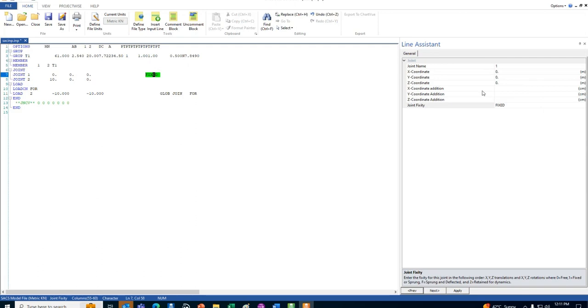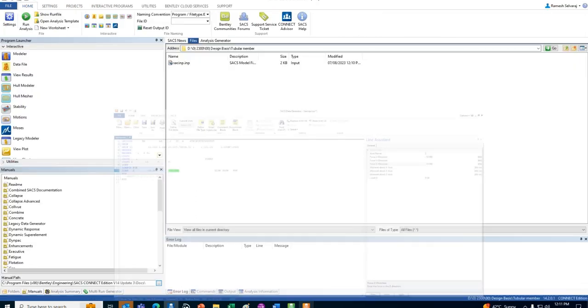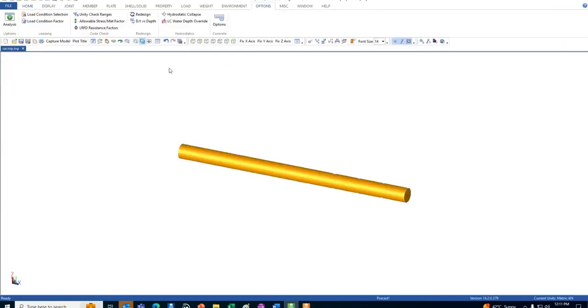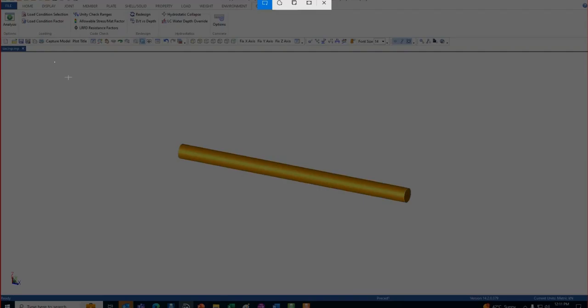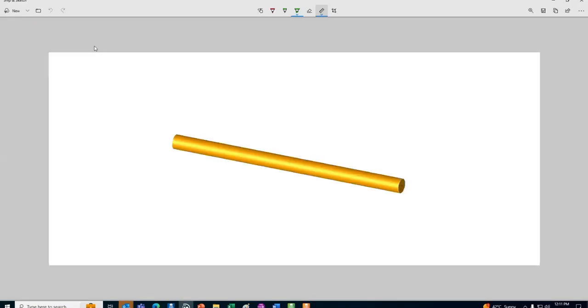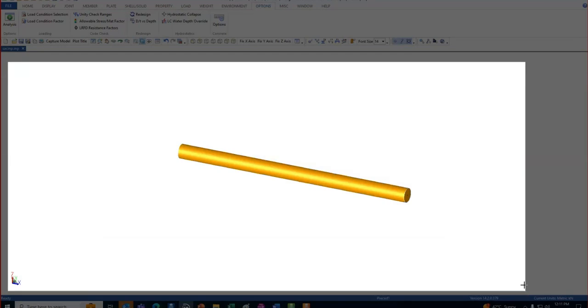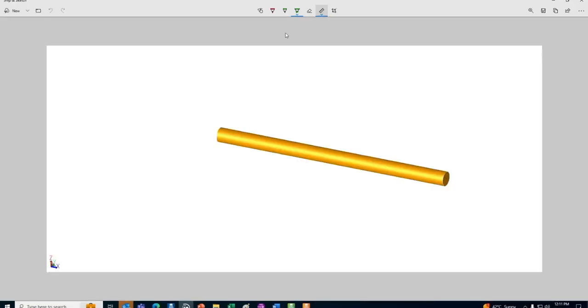First joint we have given as a fixed boundary condition. Joint fixed is the fixed one. And the load we have applied is one axial load and one vertical Z load. So when we apply this to the member, we have applied a load like this, right? So what would happen? This will make a bending. So this is the fixed end, right? At this fixed end, this is the Y axis. What is this? This is the Z axis.